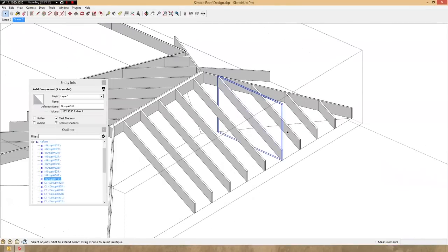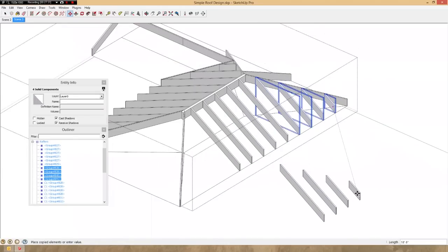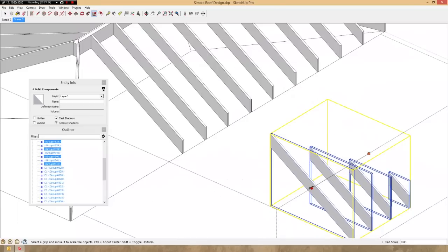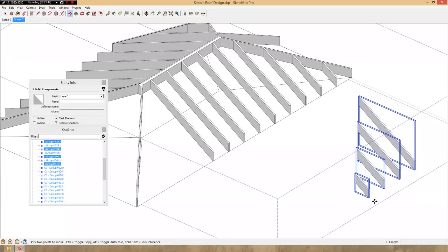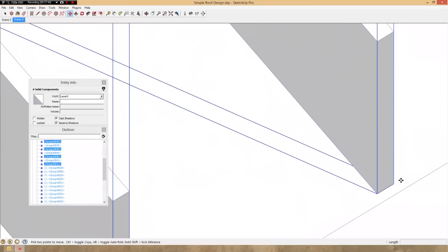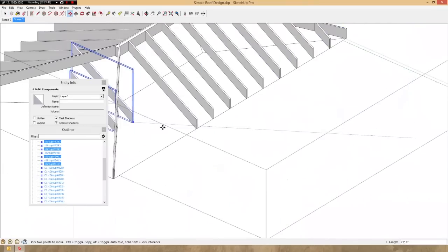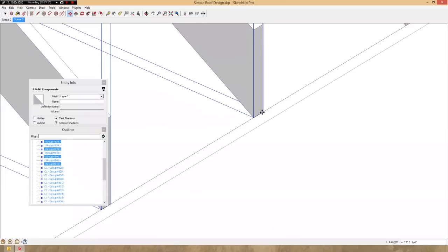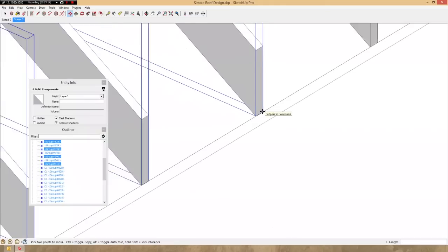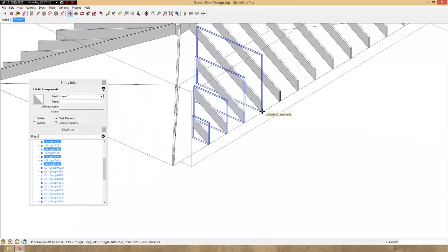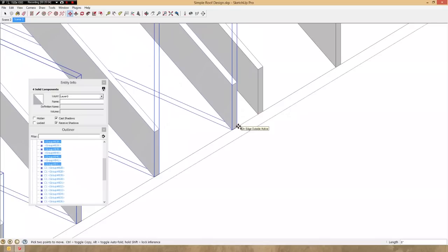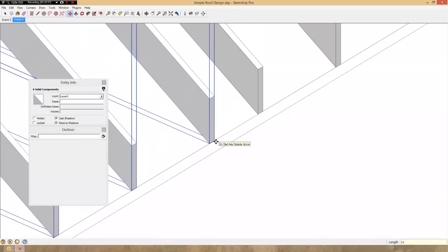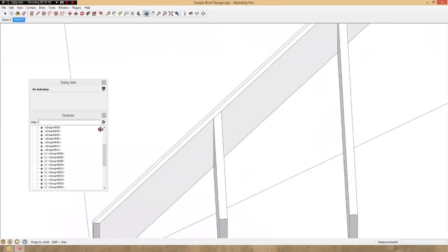Let's select these jacks and duplicate them, make them a mirror image, copy, drag, S for scale tool, -1 to reverse, M shortcut key for move tool, just locating there for convenience. And we would be moving along what axis here? The red axis. So I'm going to select and then move along the red axis. I can hit the right cursor key to lock on that axis, type in 24 for 24 inch spacing, and there we have it.